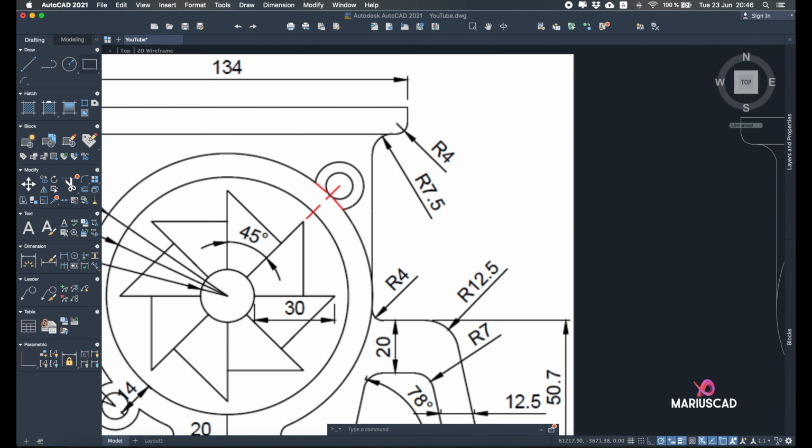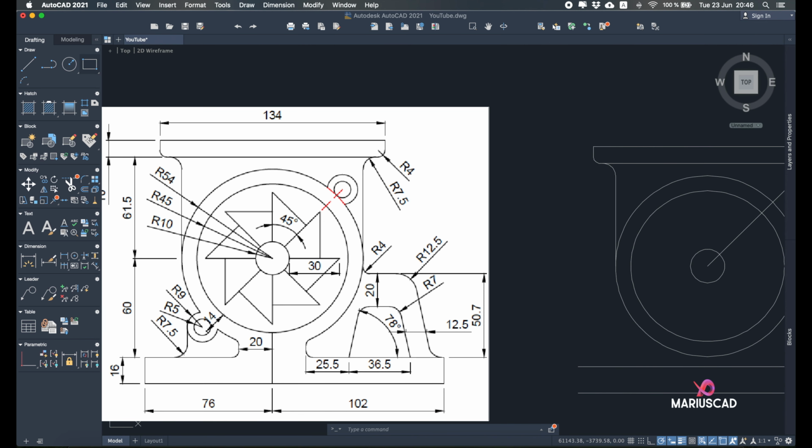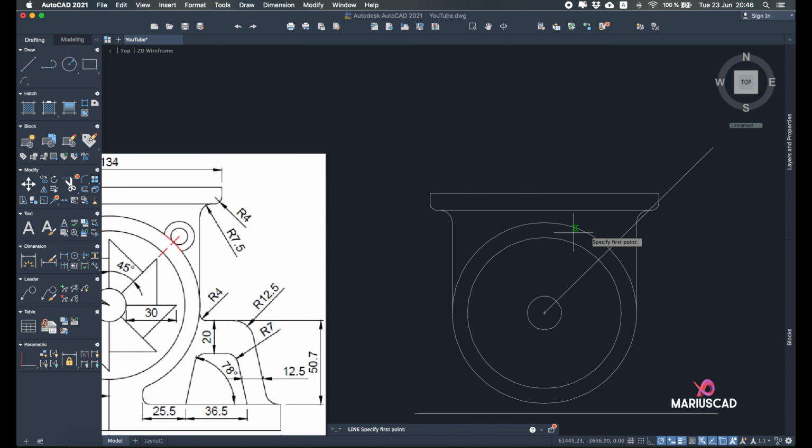But as you see here, this little circle is the same with the other one. So if this circle is the radius 5 and the other circle is the radius 9, that means this entire distance is 5. So you can trim it as well. Go with the trim command. Trim the section, the rest you can trim as well. And now, very important, go with just from the same line, the same direction, go with just 5 units. And now start to build the circles.